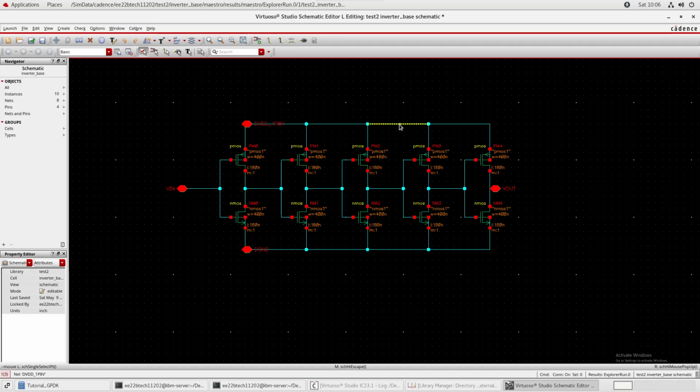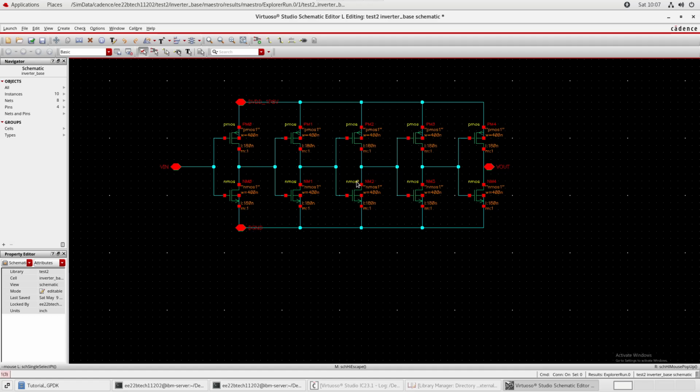So all of these nets, they're connected to DVD 1.8V. If I just hover my mouse on the bottom left, you can see the net name. Here as well, you can see the net name, D ground. The internal nodes, this I've defined, I've called it VN, fine. This I've not defined, so it just gets the name net1, net4, net7, net10. So these are just internal nets, nothing to think much about.